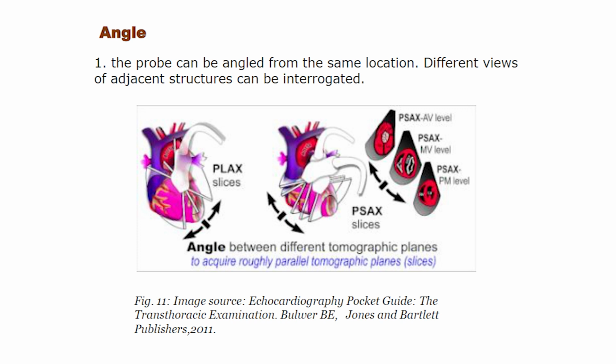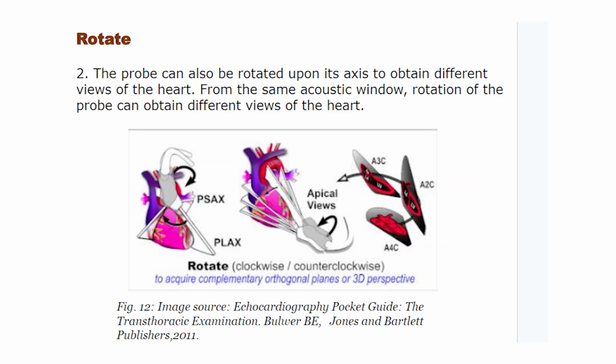Figure 8 shows commercially available linear, curvilinear and phased array. Figure 9 shows linear phased array and illustrates how the ultrasonic beam can be focused in any desired direction by controlling the phase of applied voltage to individual elements. Figure 10 shows conventional single transducer versus phased array consisting of 16 transducers.